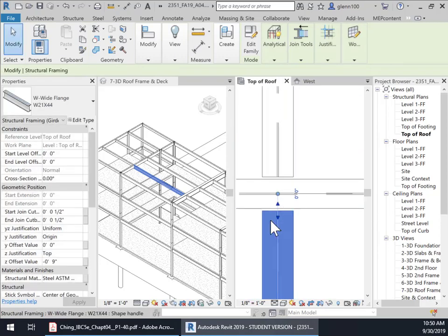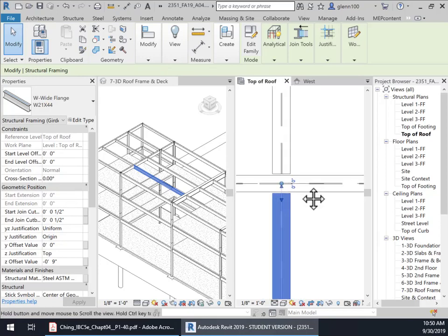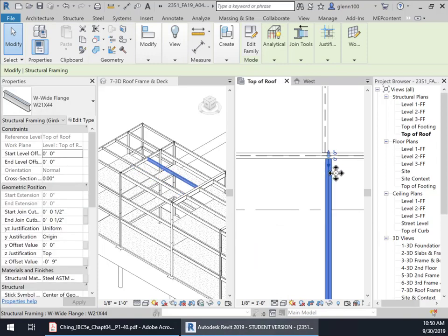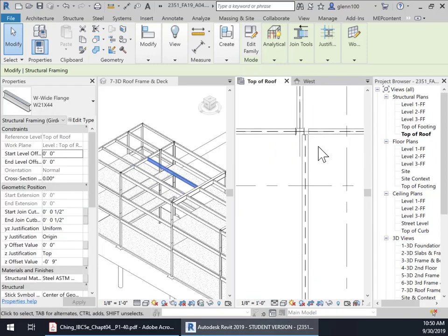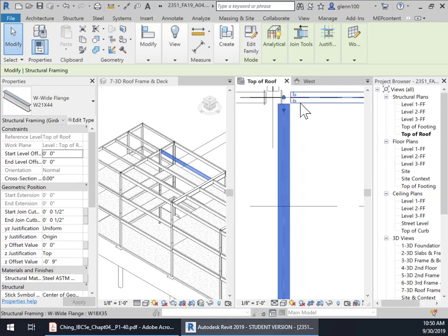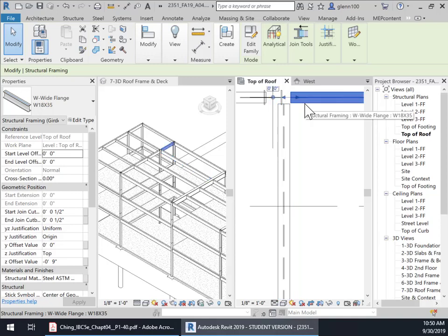Notice that even though I didn't go parallel, it won't move it except in the X direction. And then the same thing here. This needs to line up. But here's the one that's tricky. This right here, when I put this beam in and copied it and moved it up, I linked it to this particular beam right there. Okay, and I created a joint here that's really not acceptable. So we really do need to move this.